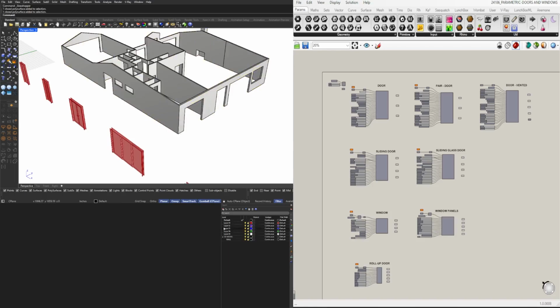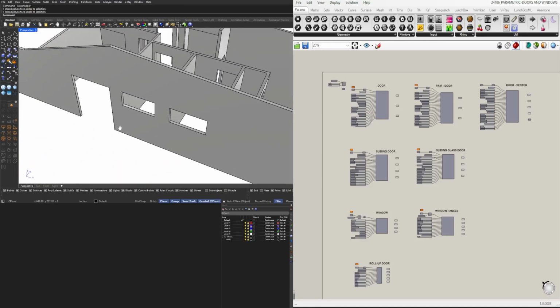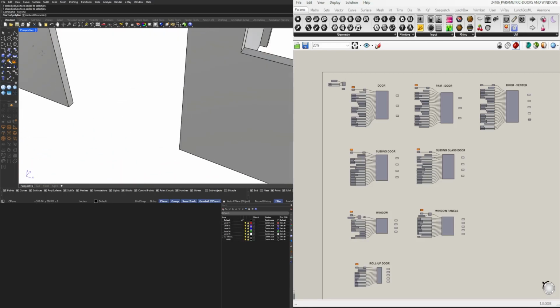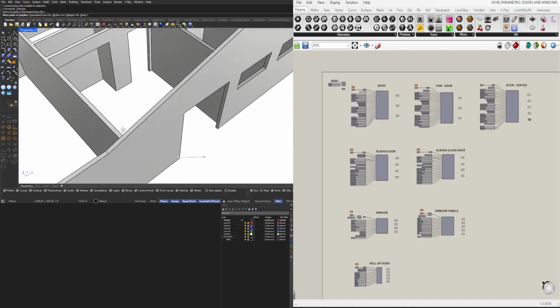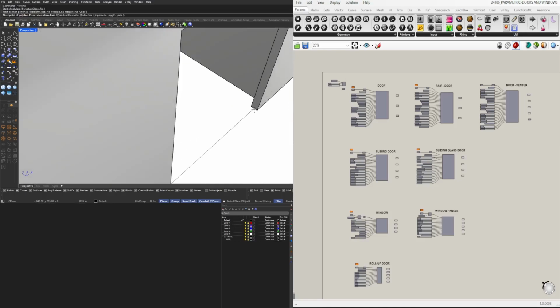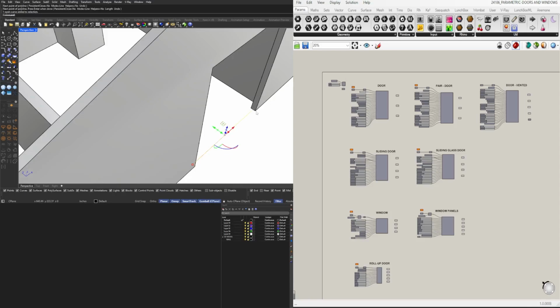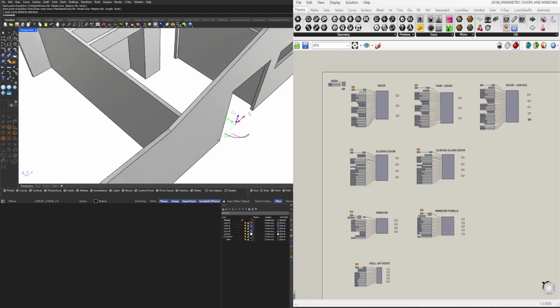So what I'll do is start here by creating a surface inside of Rhino. Now keep in mind that it matters how you create it. I'll just go to any of these layers, or it could even be on the default layer, and create a line segment between the start of the middle and the end of the middle. The reason why is because the door is created down the middle, and whenever you increase or decrease it, it's going to be off of that center line.